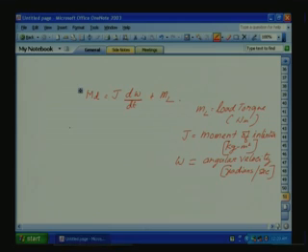Now the back EMF, EB we know it, K phi into omega. Omega is the speed, phi is the flux. For a machine, this is constant K phi. We are keeping phi constant by giving the correct excitation winding, and K depends on the machine parameter.